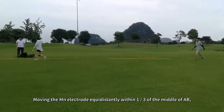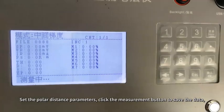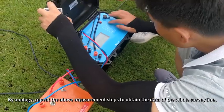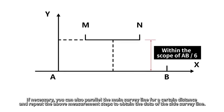Move the MN electrode equidistantly within the middle 1/3 of AB. Set the polar distance parameters. Click the measurement button to save the data. By analogy, repeat the above measurement steps to obtain the data of the whole survey line. If necessary, you can also parallel the main survey line for a certain distance and repeat the above measurement steps to obtain the data of a side survey line.